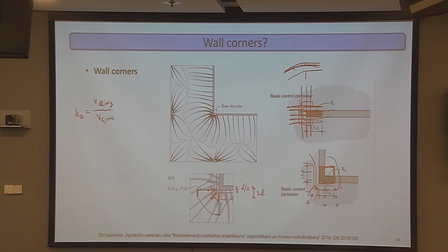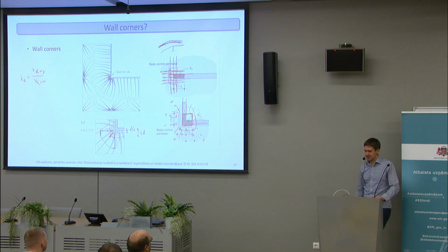So I'm not going to put shear reinforcement inside the walls or on this corner, but I will put proportionally shear reinforcement around this. That's what I've been doing in practice. Because if you put the supports in there, you can get very high moments and also very large concentrations of shear force. And I'm not sure that these walls actually make this connection so much worse.